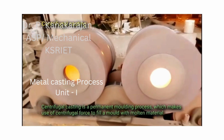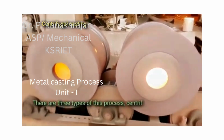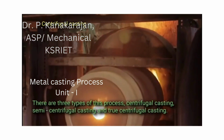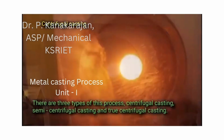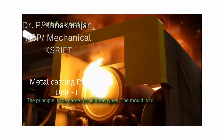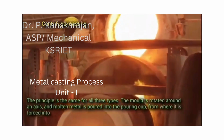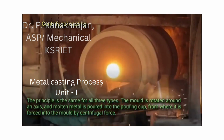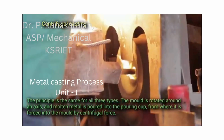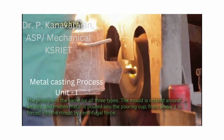Centrifugal casting. Centrifugal casting is a permanent molding process, which makes use of centrifugal force to fill a mold with molten material. There are three types of this process: centrifugal casting, semi-centrifugal casting, and true centrifugal casting. The principle is the same for all three types. The mold is rotated around an axis, and molten metal is poured into the pouring cup, from where it is forced into the mold by centrifugal force.